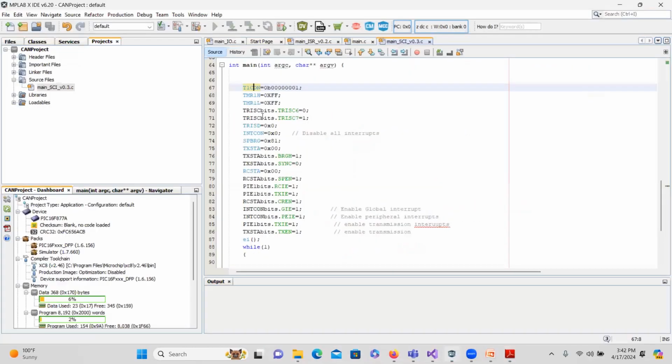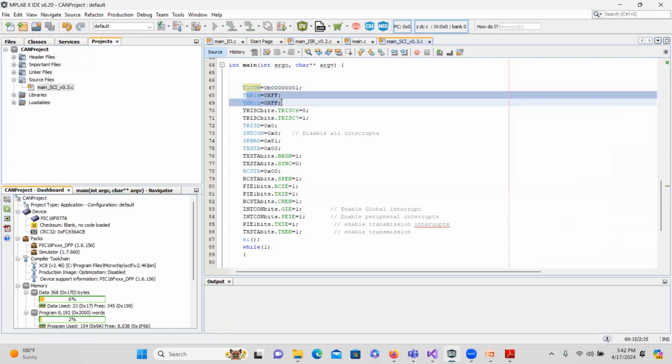That is the first step that we are doing: I enable timer 1. And then the timer counter values are set to FF. When you are using it as a timer, it will start from 0. If I have some other value here, for example 20 or 30, it will count from there. To avoid that, we assign FF so that immediately one overflow will happen. The moment it counts, the timer will become 0, and it will count from there.